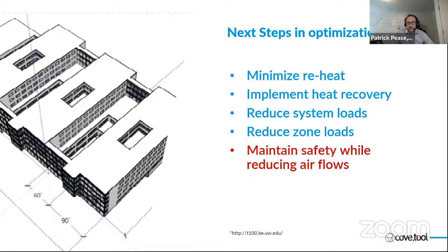Implementing heat recovery on anything and everything that you can will also go a long way for a hospital project. One watch-out here, of course, is that the simple approach you might take in an office of throwing an enthalpy wheel in your AHU isn't always an option with a hospital, because mixing potentially contaminated airstreams with supply airstreams is not allowed. It's not safe for the patients. So there are a lot more complications there, but it's still a very key energy saver.